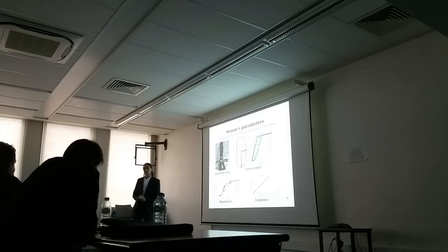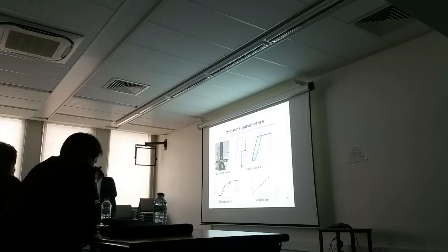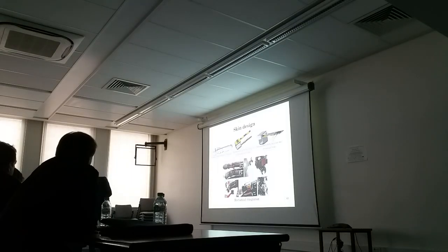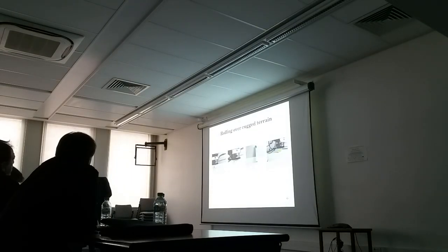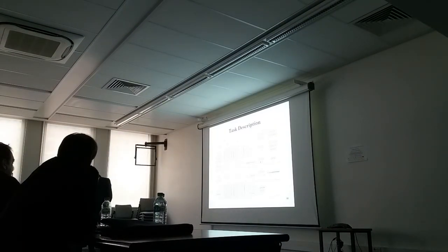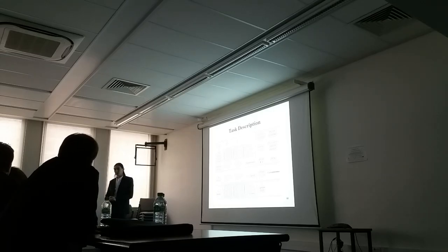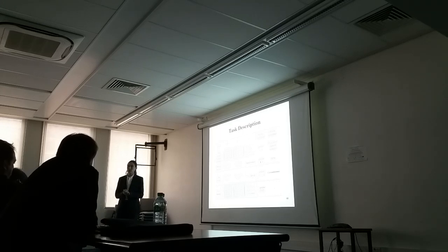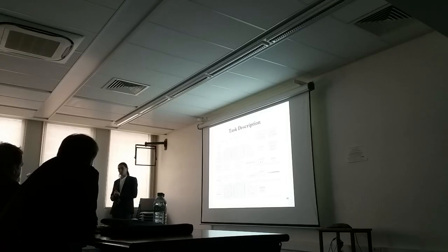And in your simulation, as discussed in the document, page 42, you present the simulation environment. Did you integrate the fact in the simulation that the sensor sensitivity is not the same in the center of the tactile sensor and on the sides of the sensor? No, the sensor in simulation was assumed to be ideal, but also in the Gazebo simulator using the Open Dynamics Engine, it's impossible to simulate deformable objects.